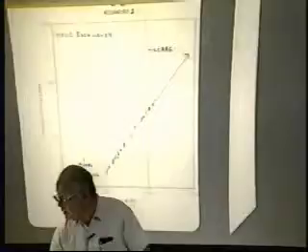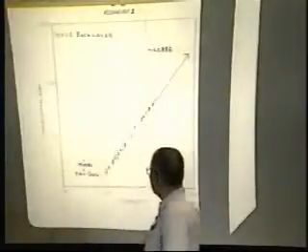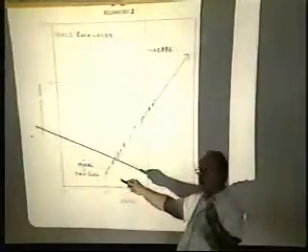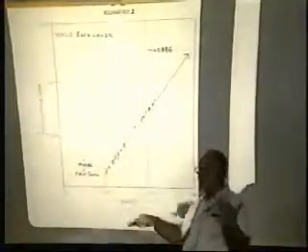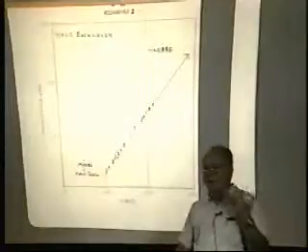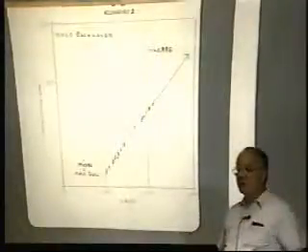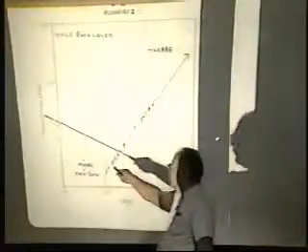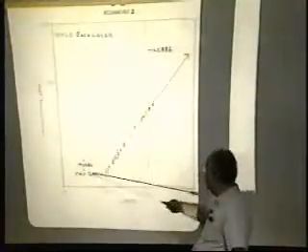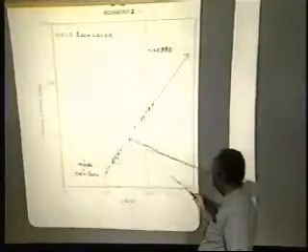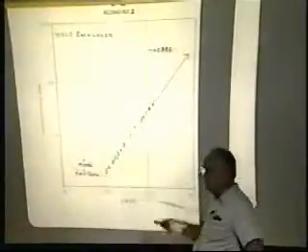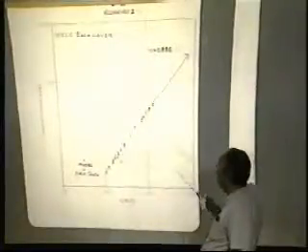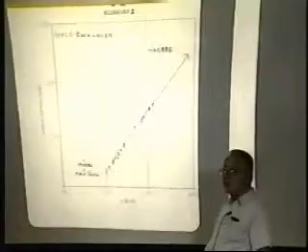Now this is a match of the well deliverability. I plot it as a back pressure curve. The observed shut-in pressure squared minus flowing pressure squared. The equation is normally built for P-bar, but I don't have a P-bar. I just have a number. It's a 72-hour shut-in pressure. And the flowing pressure and the rate, and this is a plot with the field data or the red squares. The model simulation of the shutting in and the flowing is the blue circles. Pretty good, isn't it?